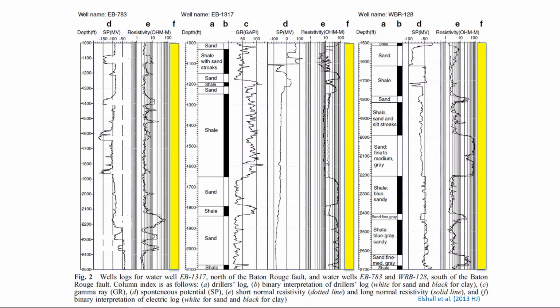Here is an example of self potential, and you see all this negative self potential here, this kick here, and here, and here. All of this indicates saline water. So if you look here, it's exactly as we expected. This would be saline water. So from here you learn about saline water.